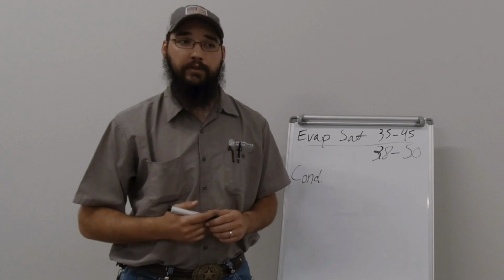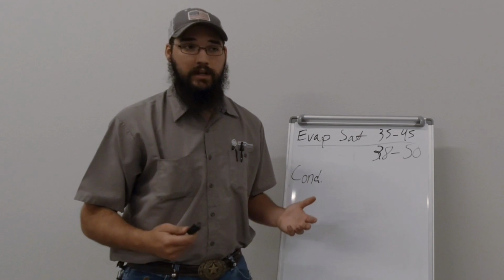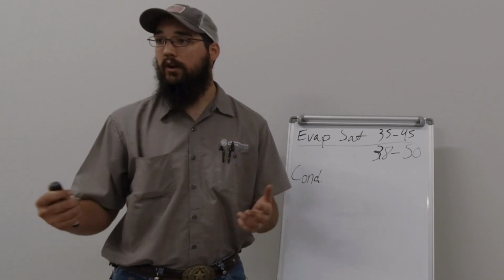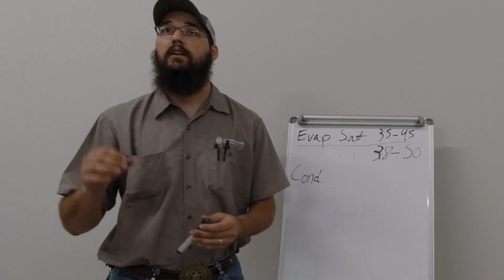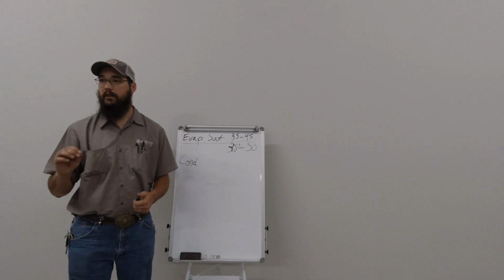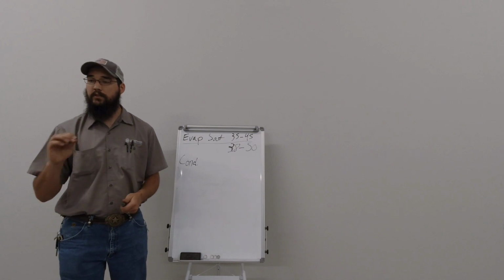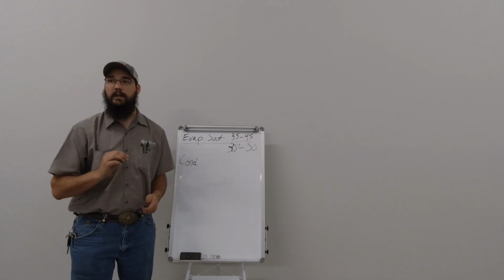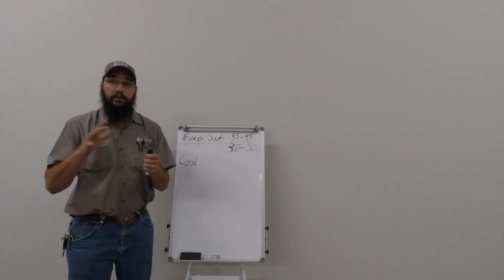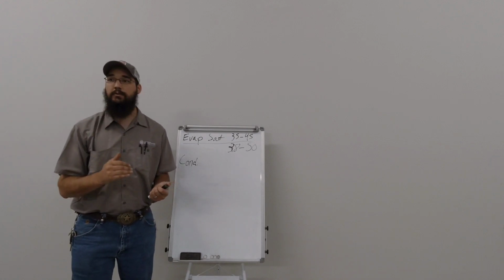Again, that comes straight back to efficiency. It's not uncommon for us to run into condensers nowadays that only run a 15 degree split between our approach on saturation differential, right? The difference between ambient temperature outside and condenser saturation. It's not uncommon to see 15 degrees nowadays, even though the rest of the system is not that high of a SEER. The whole point for that is strictly to try to get that compression ratio down.